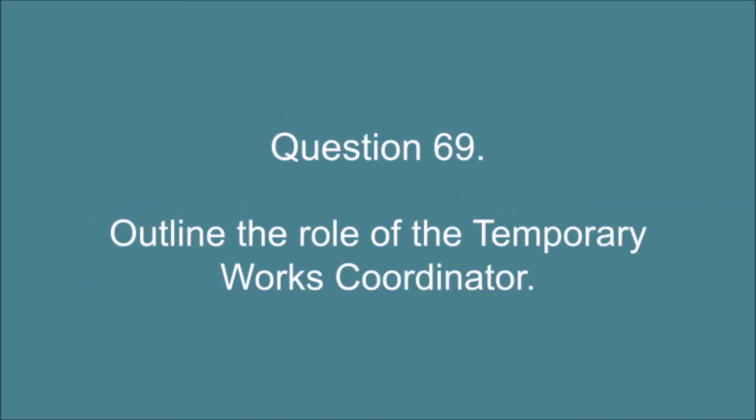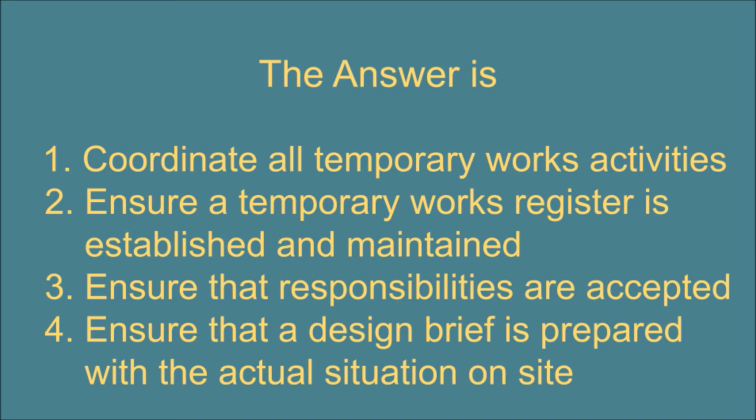Question 69. Outline the role of the temporary works coordinator. The answer is: 1. Coordinate all temporary works activities. 2. Ensure a temporary works register is established and maintained. 3. Ensure that responsibilities are accepted. 4. Ensure that a design brief is prepared with the actual situation on site.